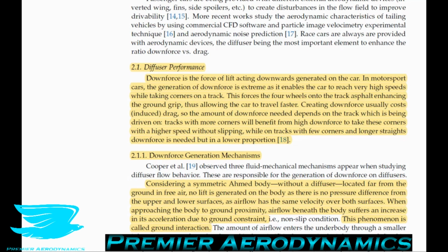They're coming from flow being pulled and torn at the surface of objects, which creates vorticity and vortices. So you do see vortices on cars that look like induced drag, but not actually induced drag, and that's called vortex drag. Interestingly enough, when you measure induced drag in a wind tunnel or on CFD, you can use the exact same equations on both, but they're technically two different sources of drag. So that's what they mean by induced drag.